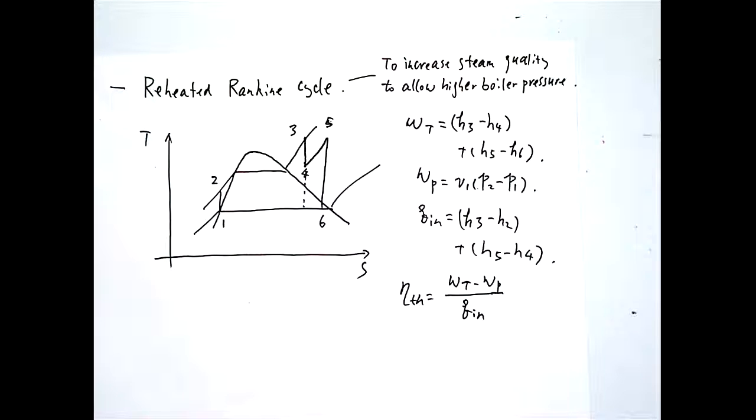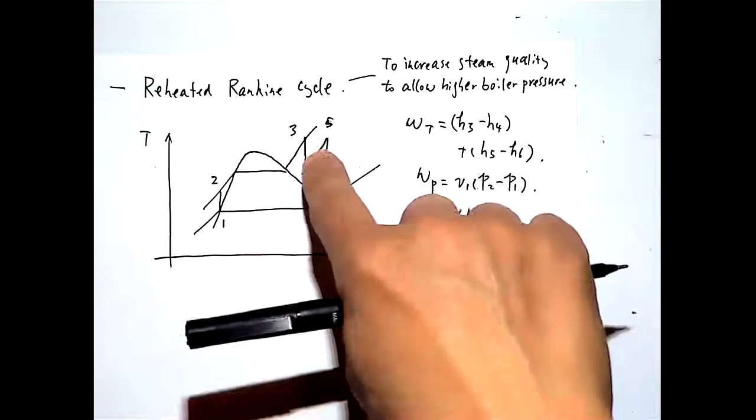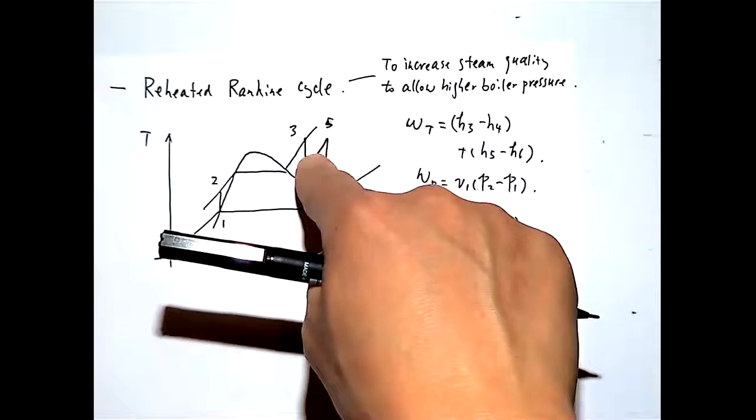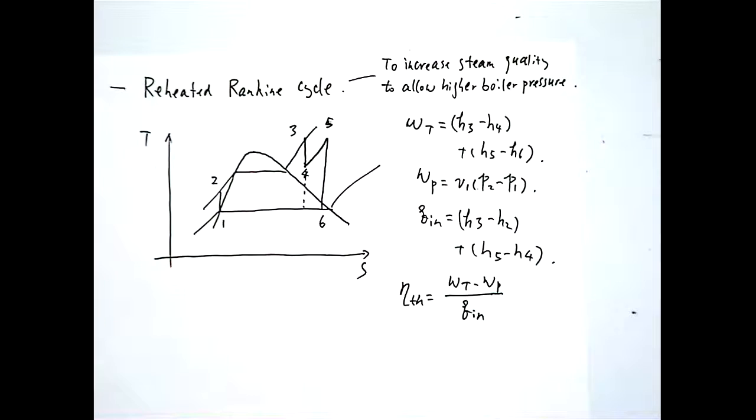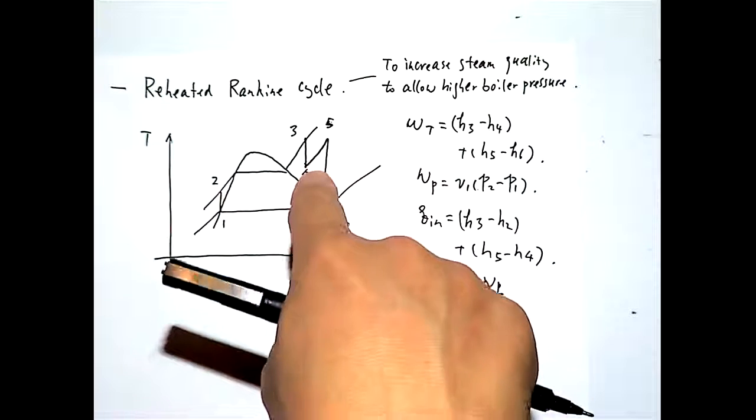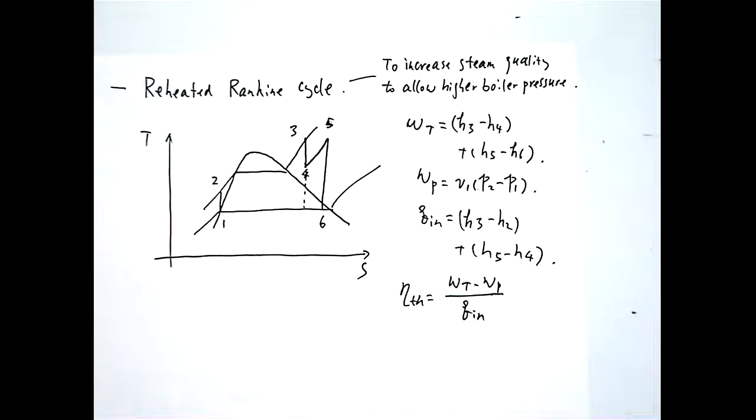Jet engine, of what? Afterburner, yes. Afterburner is one place that we saw this, and I heard regenerator. Yeah, but regenerator does not have additional heat added. Reheater, yes. Reheater is a place you add additional heat. But all three, the turbojet, the reheater in the Brayton cycle, and here, are working for different functions or different purposes. Right?